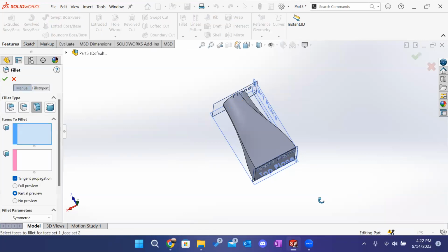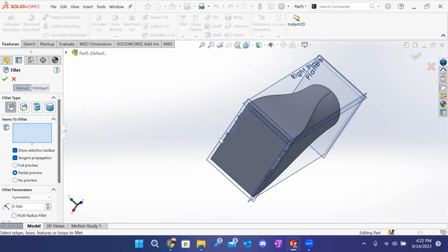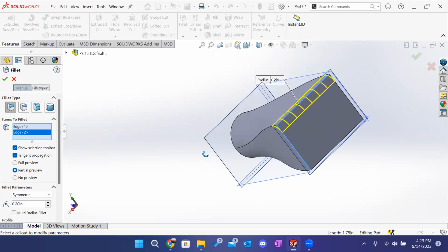So a fillet, again, we made one earlier. Right now, you have different options when you're in the part mode. So you can do it while you're sketching, or you can do it after you sketch. Right now, it's giving me different options. So I can choose this part right here, and it gives me a preview right away if I want to make the radius bigger. And here,